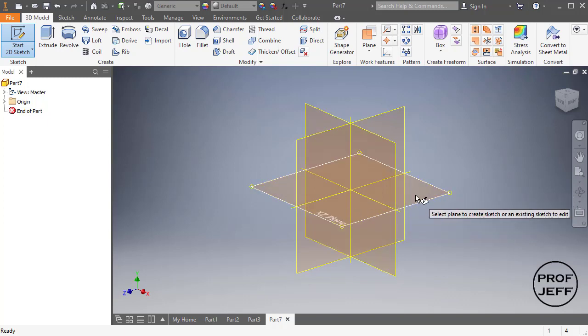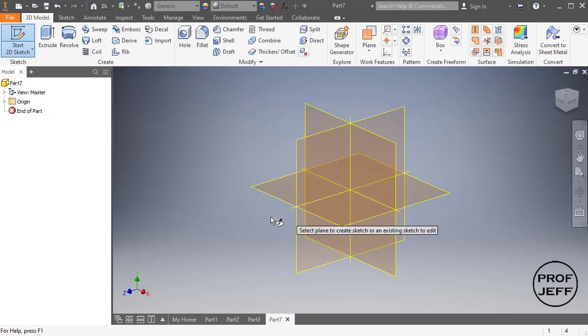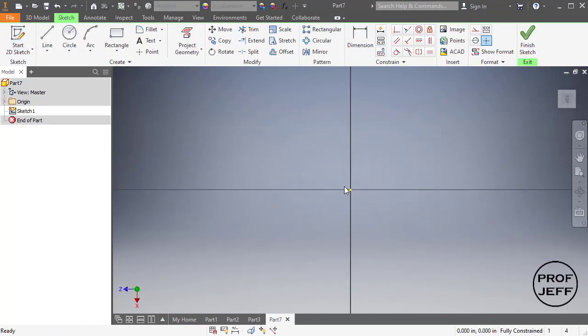Now the other thing that I really want to point out here is that we need to watch the coordinates here. So the Z is coming in this downward direction here, and the X is in this cross direction. And the one thing that I'll point out, when I click on this plane and it rotates around, we would typically think that the in-out direction is going to be this way in the X direction, but in reality it's in the Z direction. So honestly, this view is rotated 90 degrees.